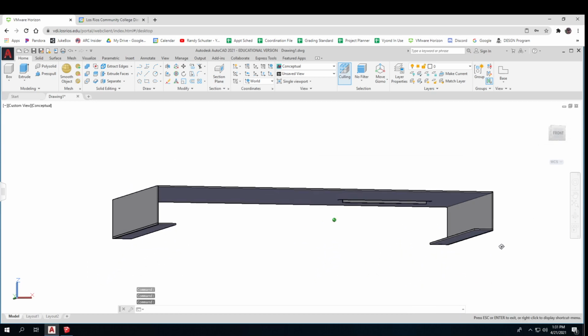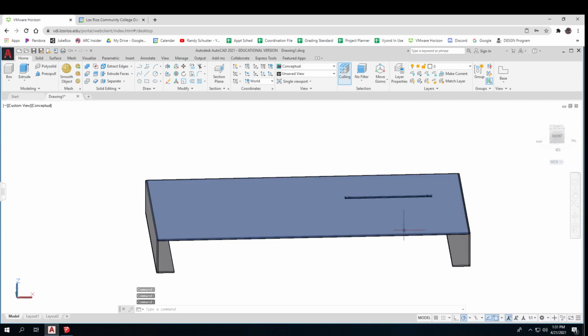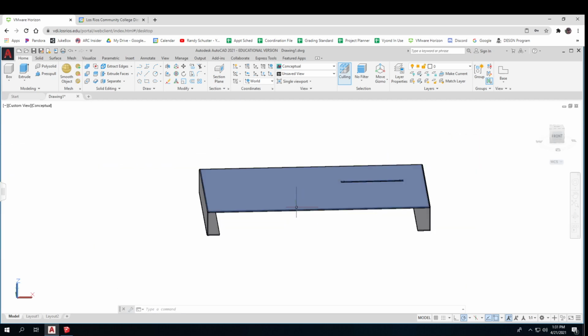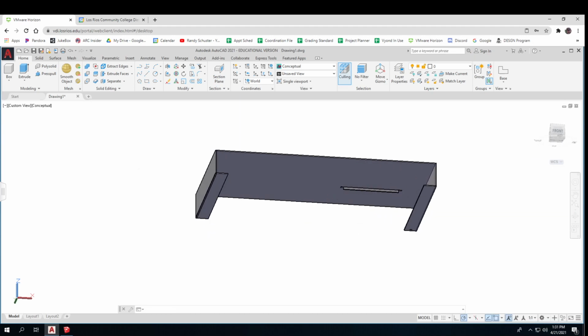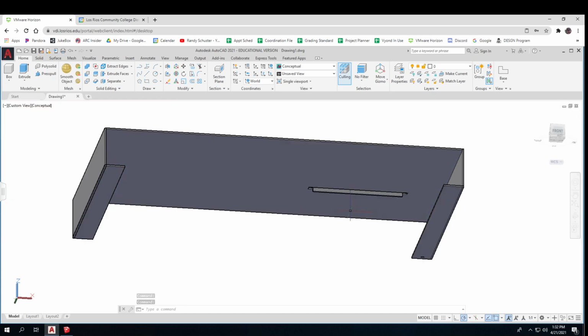See how that little piece would come down? And so you know that that would stiffen this up. And I could even do one of those up here. So I could do those here, there, and everywhere, and it would totally, totally stiffen this thing up. And you don't even have to make them straight across. You could put them at cool angles. And it would not keep you from putting flat things on the top, but it would add stiffness to this through the strong back. It's called the strong back.